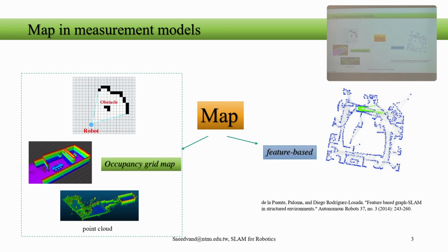But today we want to see in detail how we can use the Bayes filter and the probability concept to fill this in: how certain we are that there is an obstacle here or not. It's not always 0 and 1. If we were that certain, the problem would be solved.